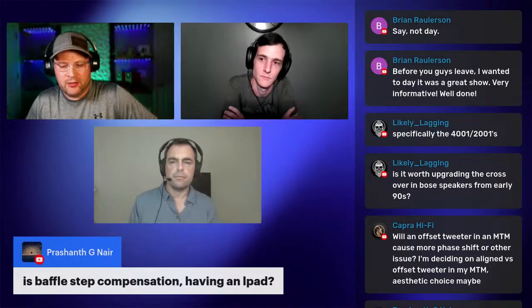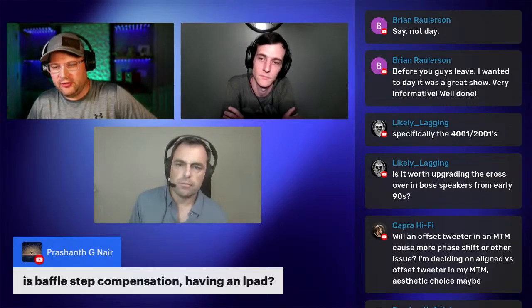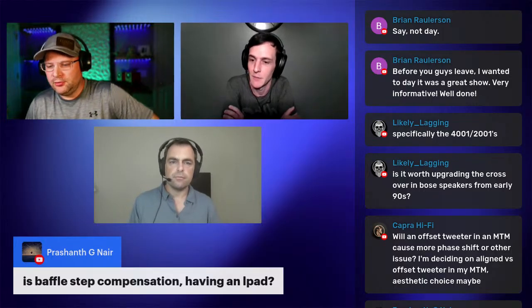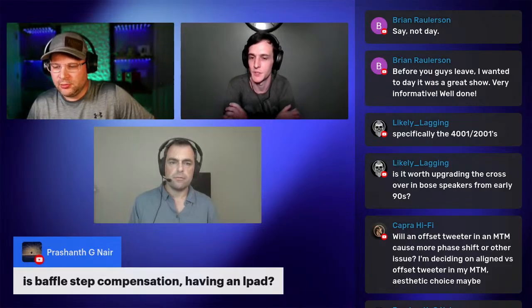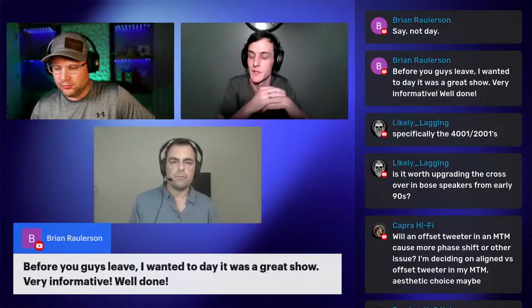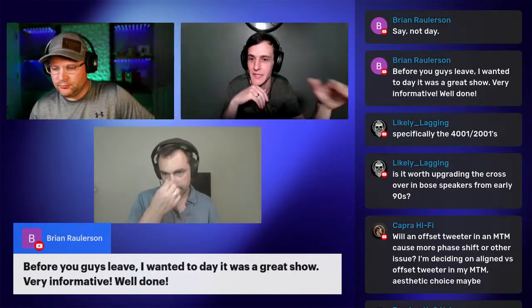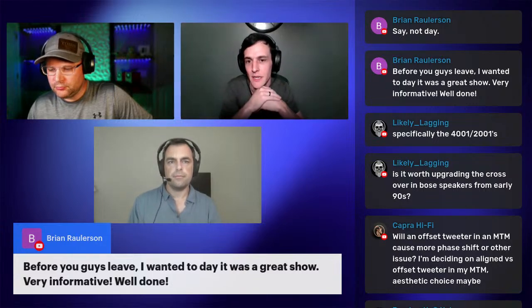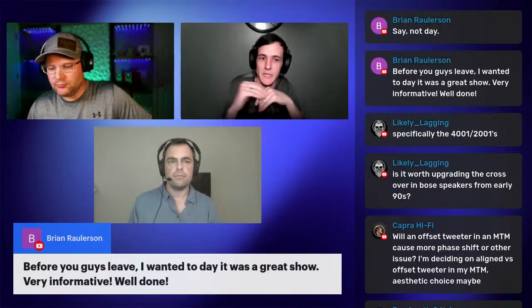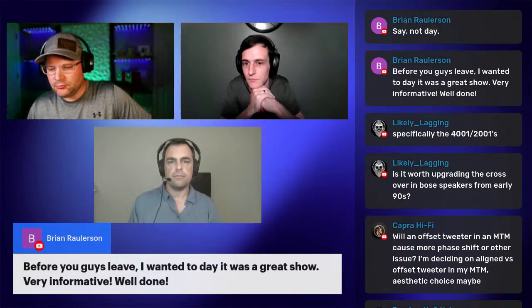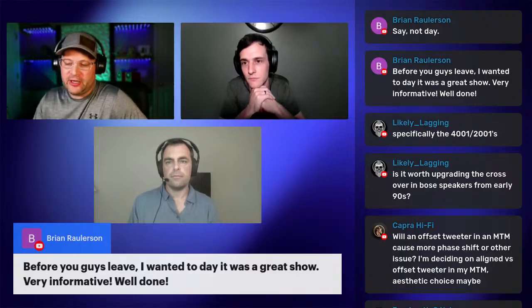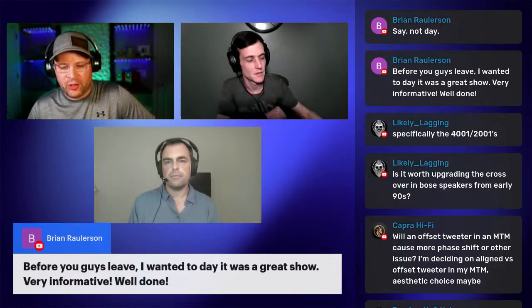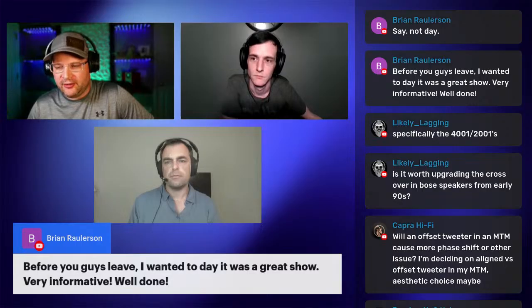I think me and Ryan would say the same thing. I think you would say the same thing too. Just use whatever low pass you're doing, let that affect it. Baffle step comes from before we had the ability to simulate, and they had to assume that the baffle diffraction was going to occur at some frequency, which it still does, but we can see exactly where that is, and we know how we're shaping it. And an LPAD is just specifically for attenuation, so that wouldn't necessarily be your baffle step. That would be most likely in your woofer or mid-range circuit. But you would take that into account in your crossover, absolutely. You would use your low pass for that. So whatever low pass circuit you use is going to take that into account.